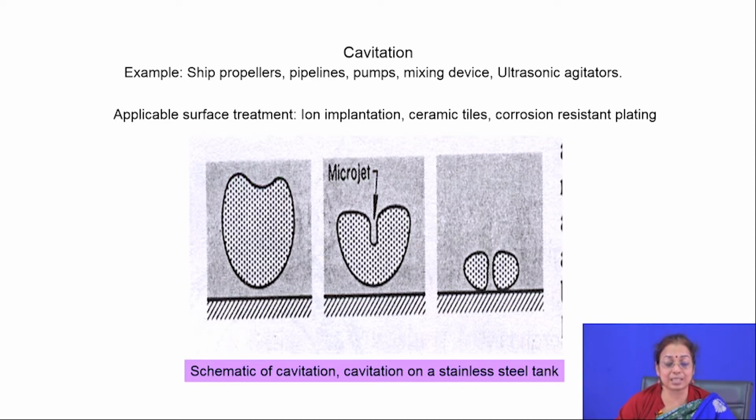So, when those gaseous bubbles meet the solid surface, they burst. When they blast, there is again a drop in pressure in the blasted region. Because of this drop in pressure, a lot of liquid from the surrounding zone flows in, and they cause the erosion process again at a much more rapid rate.